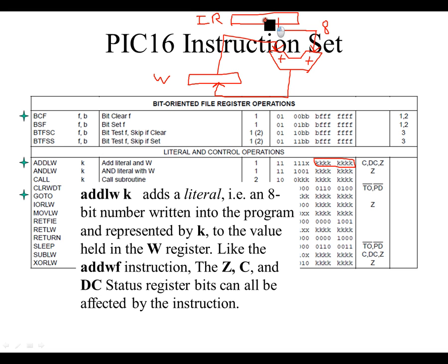These bottom 4 bits we're designating as K are in the instruction register. And then the rest of the instruction, 1, 1, 1, 1, 1, X just means it's not used. They don't really care what it is.